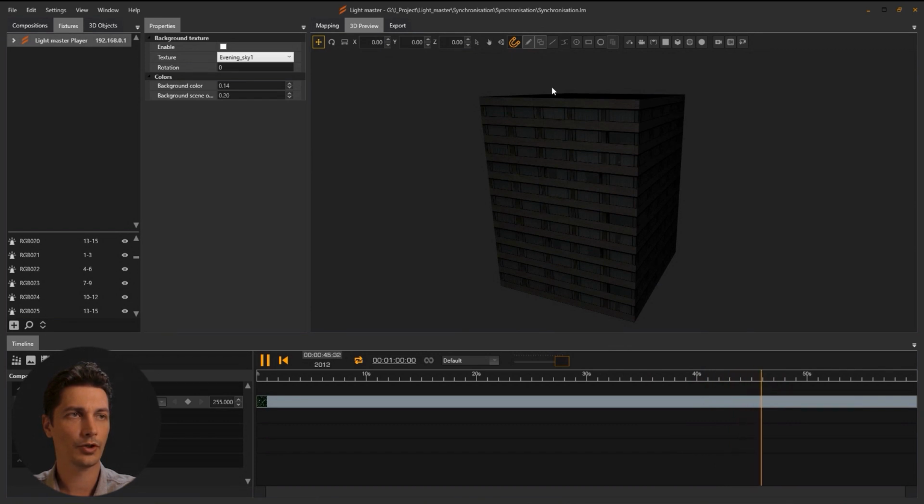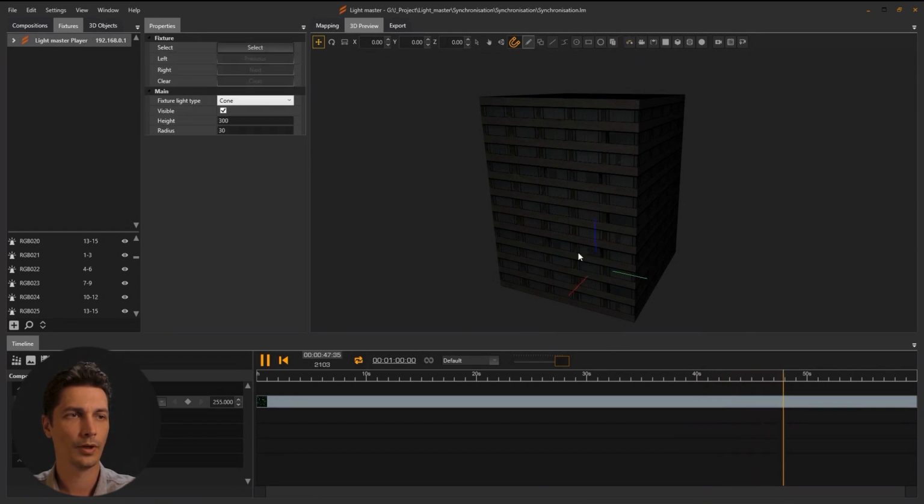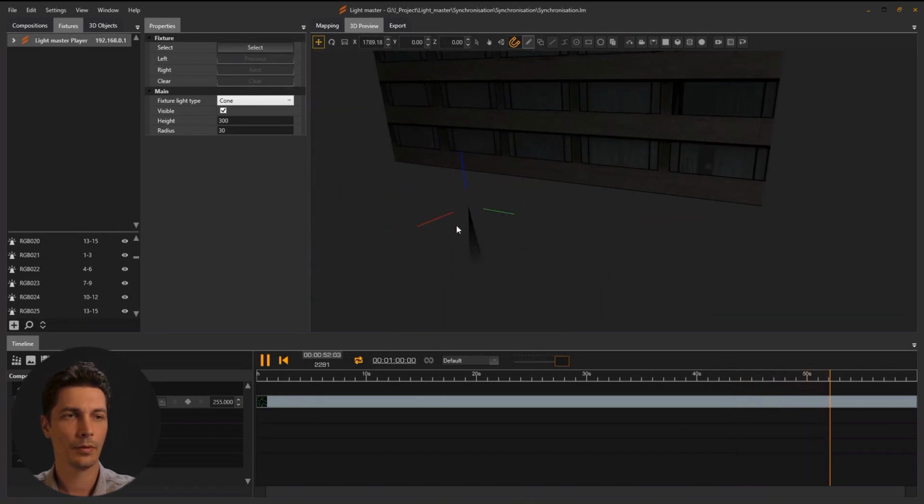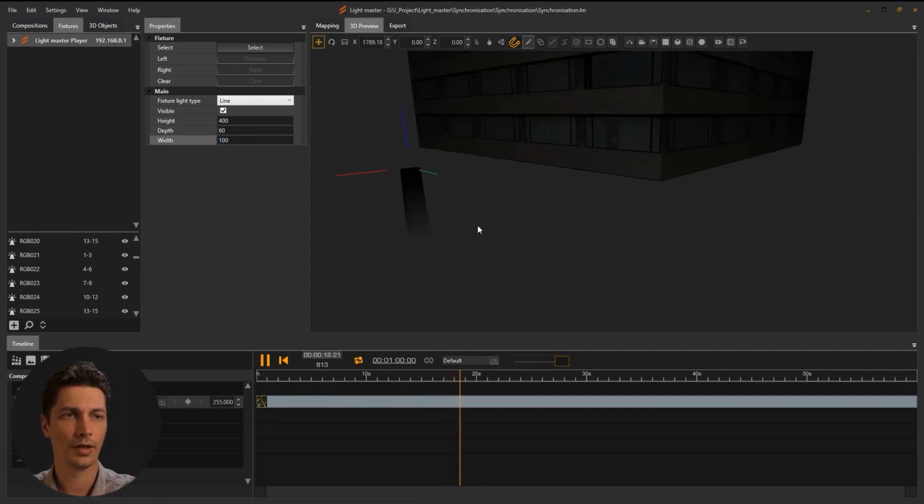You can create fixtures by clicking on the Create from Fixtures button and selecting their type. It can be a spotlight, in this case a U. The beam's length and the opening angle are adjusted to meet the specific requirements. Alternatively, it might be a linear luminaire, which also sets the length of the beam. The angle at which the luminaire opens and the overall length of the luminaire are important factors to consider.